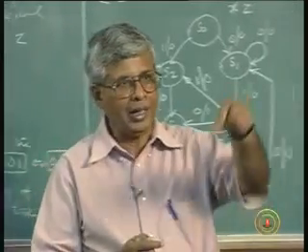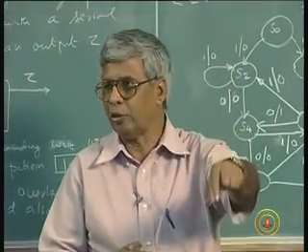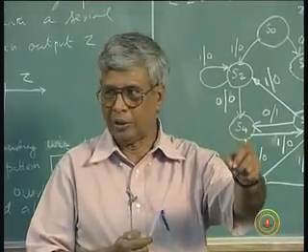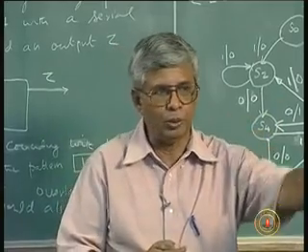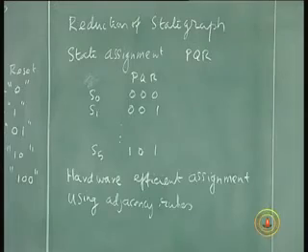I have to buy and put in an IC. One AND gate means one extra thing I have to put. One multiplexer, one extra thing. One flip-flop, an extra one. For each one I have to go and buy an IC and put it there. It takes more space, more power, more money, more everything. Speed is reduced. So in those days hardware reduction was very significant.